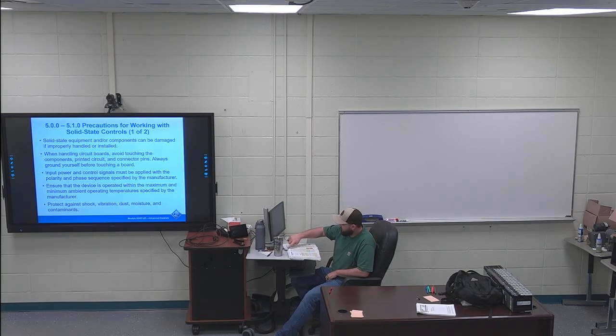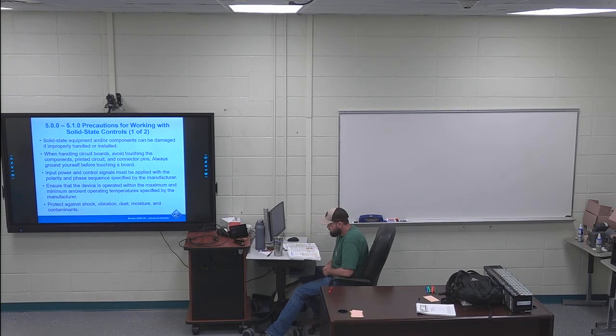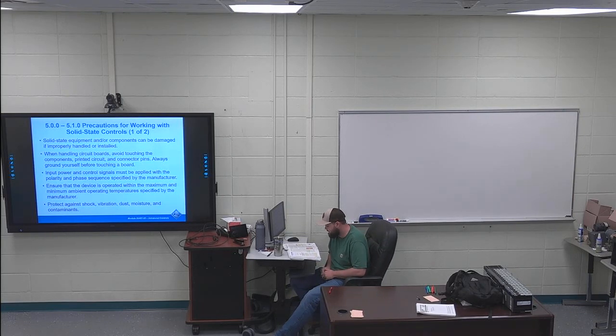Right after the first set of bullet points, I got that whole paragraph in between sets of bullet points on page 40 on the right hand side highlighted. Electrical noise can also affect the operation of solid state controls. Sources of electrical noise include machines with large, fast changing voltages or currents when they're energized or de-energized, such as motor starters, welding equipment, or adjustable frequency drives, and other inductive devices. Following are basic steps to help minimize the electrical noise.